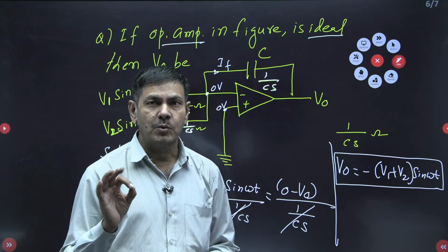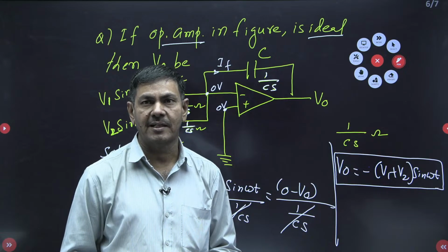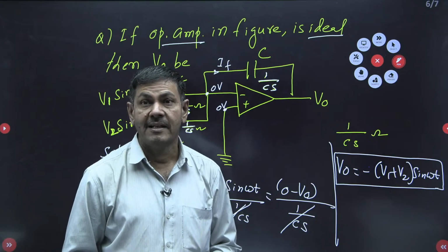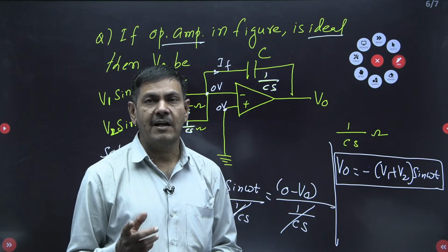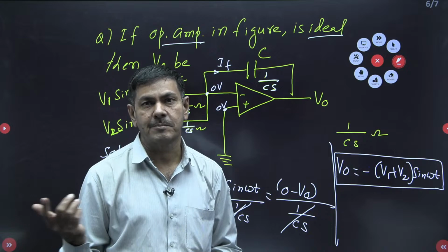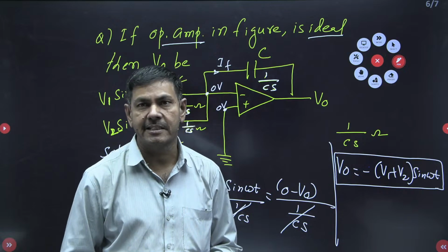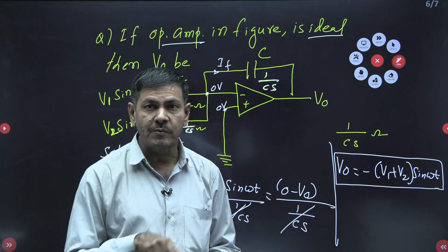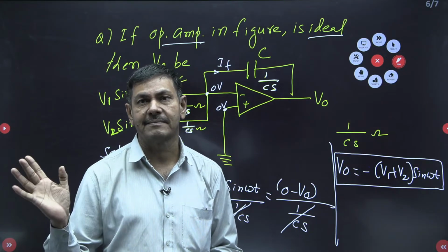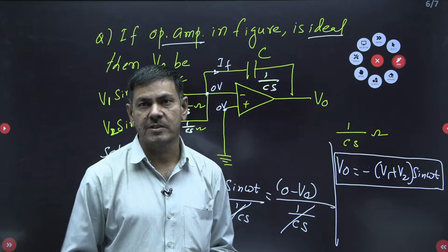To design any oscillator, at the time, it must satisfy two conditions. They are said to be Barkhausen conditions. You know very well. Phase shift attained by the signal must be 0 degree or 360 degree. And second one, loop gain is also very important. The loop gain must be unity. A beta equal to 1 is a must. Using those conditions only, we can do the questions.